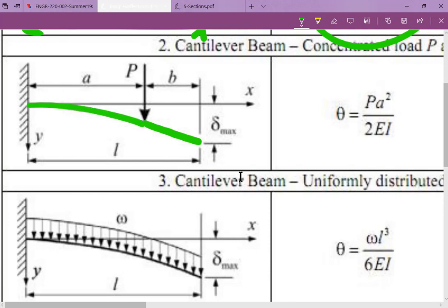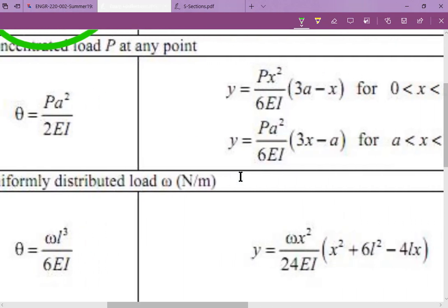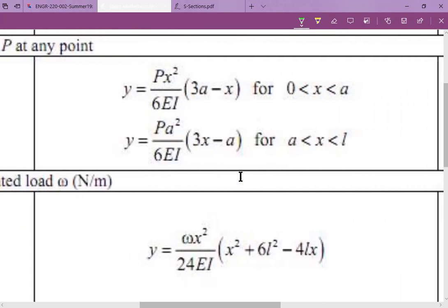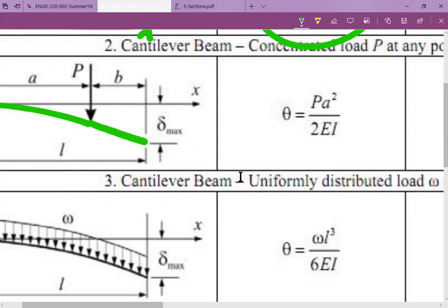They might not be including the self weight of the beam because they don't have anything to help you include that, but they are doing something a little bit different than what we did. But we're saying that this, let's make it a different color, that section, the red one, is a linear slope, whereas the section from the wall to the point load actually curves. That's how we're going to treat it, and that's how our web work does it.